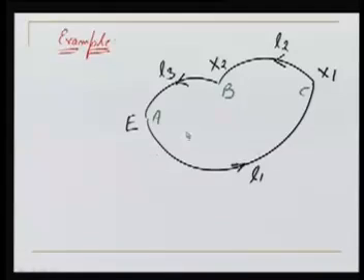Similarly, starting from B, I can go to C, and then again I can find the RL difference between point B and C. I add it to the RL of B, and I can find the RL of C. This way we can determine these two, B and C, their RLs. One more way is possible. I can go straight from A to B as well as from A to C. So what we are seeing here, we are doing the same thing.